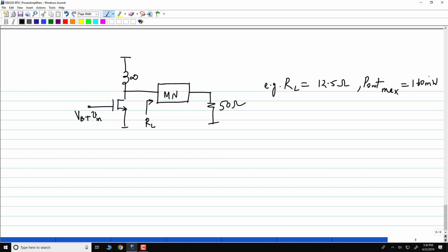These are all standard ways you can try to put stuff together to do it. Now, of course, this matching network will also be an L match or a T match or a pi match, right? The matching network, as before, will make the circuit fundamentally narrow band. The circuit itself is wideband. Both the inverter circuit and this circuit are wideband circuits.